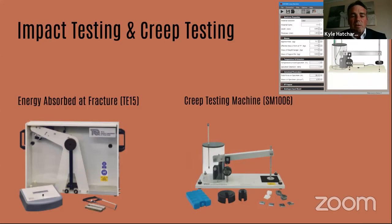So you're moving the material from the elastic property, from the elastic limit. So if you go back to that original curve that we're thinking about in the linear section, and then eventually as the material elongates, it reaches its yield point, and then extends through the three different stages within the creep test. Just really similar to Young's modulus, but it's all about a constant load that's being applied. And these tests do take quite a while if you've got the strongest types of material. So nylon, for example, is very easy to visualize because it stretches quite quickly with a low mass. However, that depends on the size of the specimen and the thickness and all those parameters.